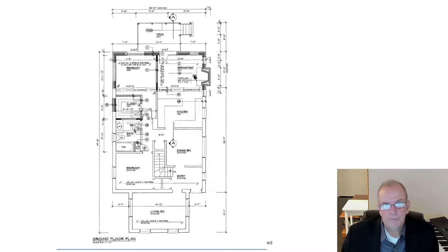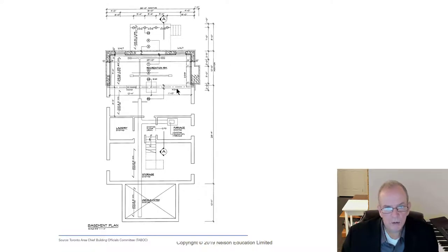You have the first floor here, and so this is right above, and again, this would be the back of the house. So the whole brick wall at the back of the house is coming out. Well, when you take out this wall, you're going to have to put a temporary wall across here to support this floor, because the first floor is resting on this wall. You can't just take this wall out without the whole back of the house falling in on you. You would have to put a temporary wall across here.